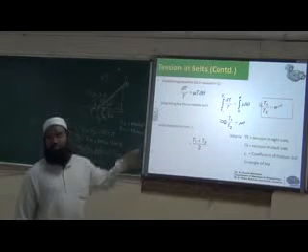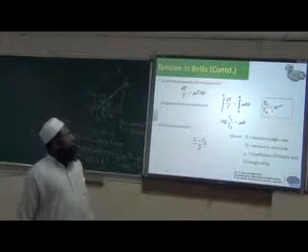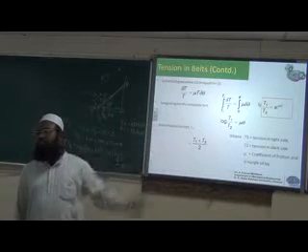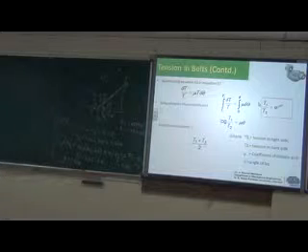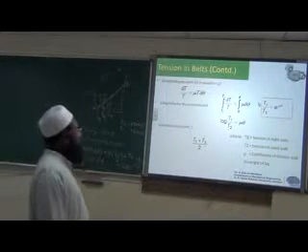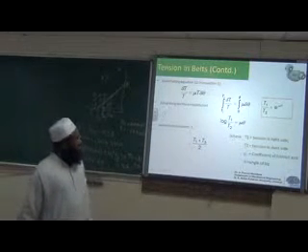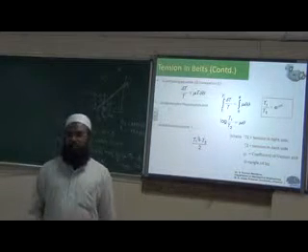This equation is important in the case of belt friction. The belt friction depends on the tension between the two sides of the belt, slack side and tight side. So you take down T1 by T2 equals e power mu theta, and the initial tension we keep in the belt is given as (T1 plus T2) by 2.